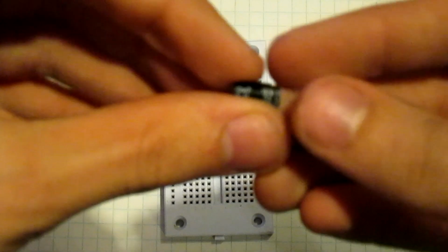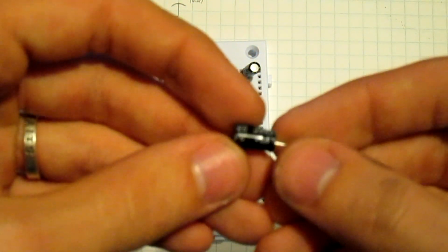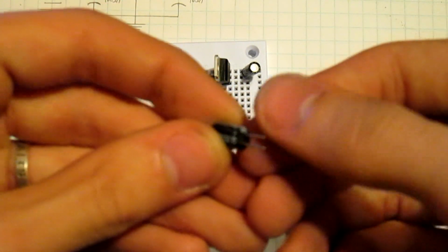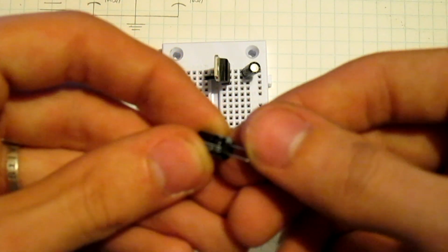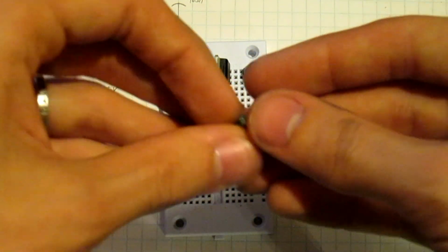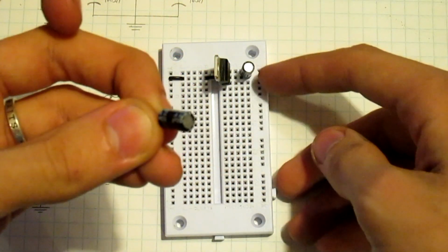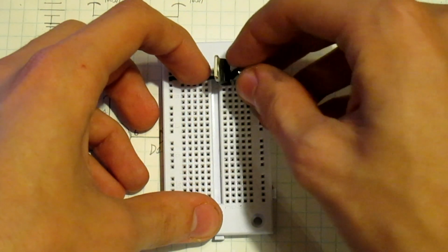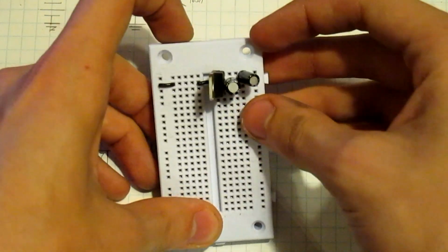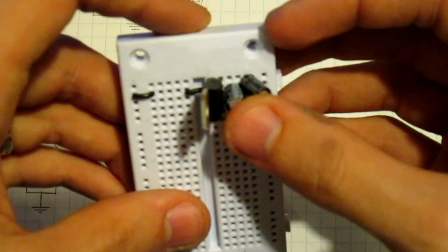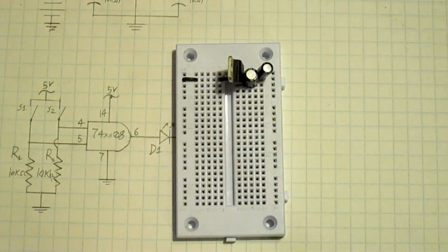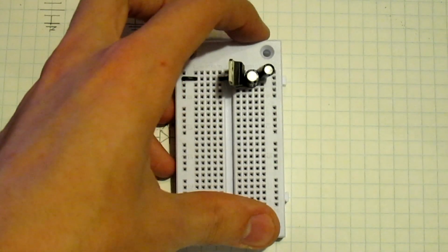Next, you want to get another capacitor, and this is a 100 microfarad capacitor. Go ahead and locate the stripe. The leg with the stripe, or the leg next to the stripe, goes on the same hole as the other capacitor's stripe leg. And so on this one, the stripe will go up, and on that one, the stripe's going down. And insert it. There should be one hole above the second capacitor, like so. Awesome. Oh, forgot a step.